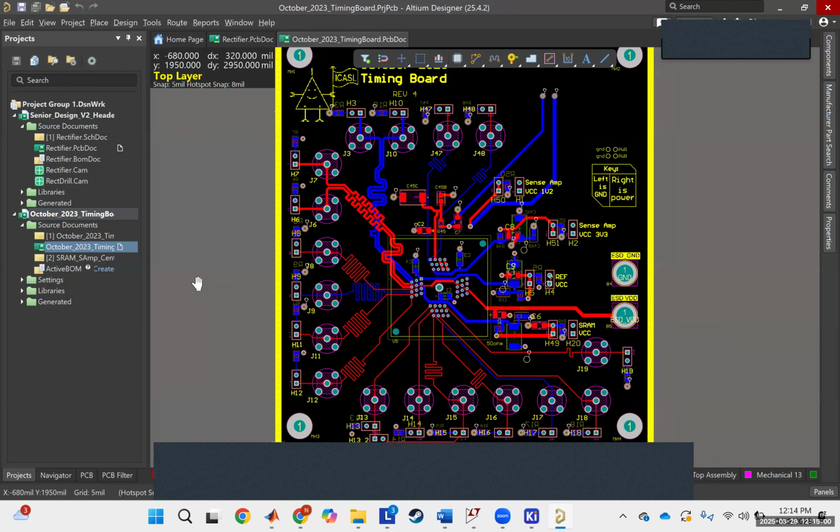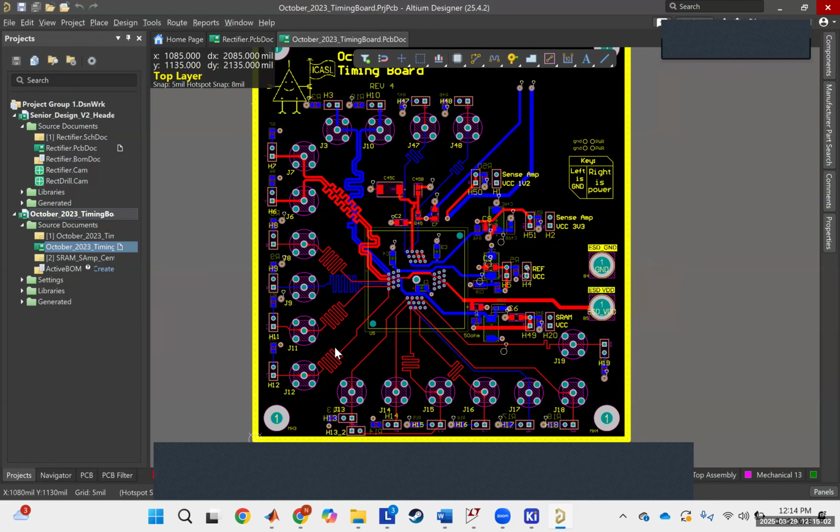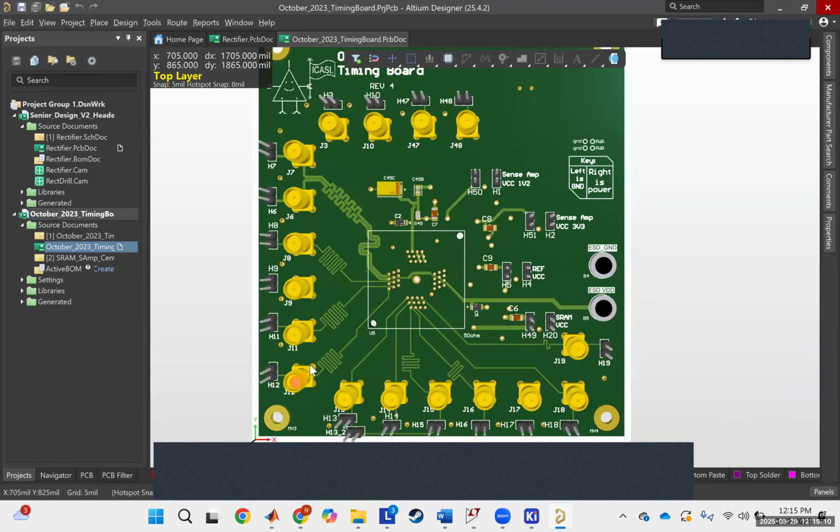So here, you can see all these little squiggles. This is called link tuning. The important thing about these digital signals is you need the signal that you put in at these SMAs right here. You can think of these almost as the headers, but it's a big, strong header. You put a signal in here and you want it to reach this thing called the DUT, the device under test. You want them all to reach the DUT at the same time, or else